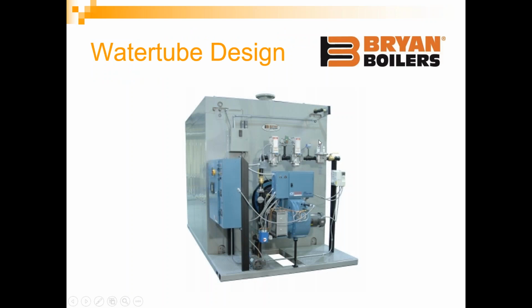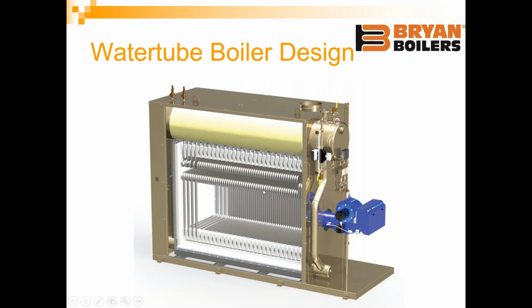Another type of boiler out there is the water tube boiler. We represent the Bryan boilers. They make what's called a flex tube boiler. Now, the flex tube boiler, a water tube boiler, does not have as much water volume as a fire tube boiler would, and it typically wasn't as efficient. But as you can see, there are bent serpentine tubes within a water tube boiler. The tubes were swage fit into the steam drum, or top drum in the hot water, and into the lower drum, which meant you could replace each one of these boiler tubes without needing to do a pressure vessel repair. And since this had those bent serpentine tubes in it, it was very good at accommodating thermal shock.